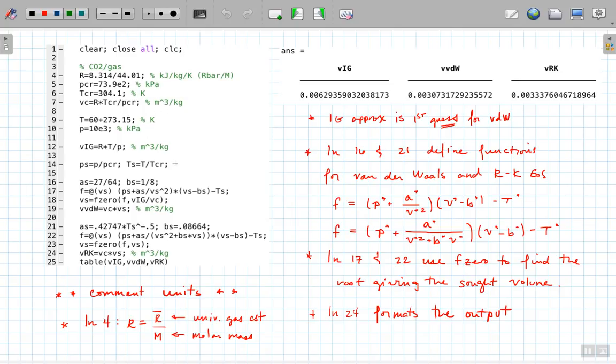Doing that is nice because basically once we non-dimensionalize by dividing by the scalings, things become dimensionless. To get things back into a dimensional expression, we multiply by the scaling. So the starred quantities are percentages of the scalings. So if we have a starred quantity, we multiply by the scaling to get back the dimensional quantity.